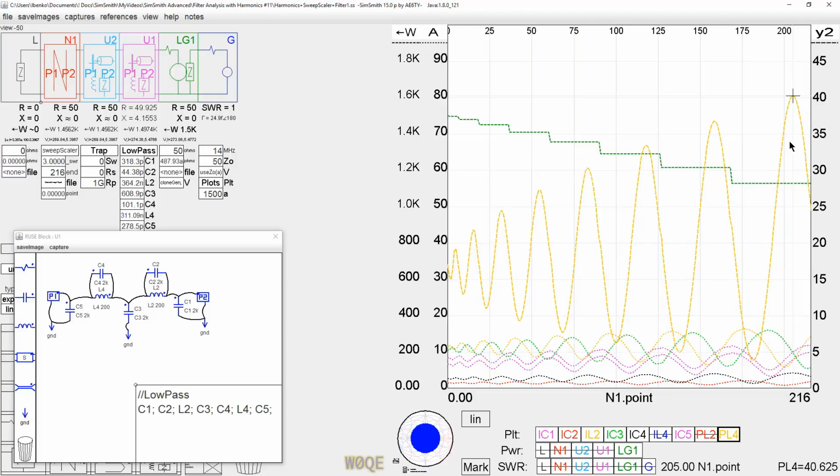We saw before the numbers were lower than those, but this is the effective SWR. The power in the inductor down here at low SWRs would be no more than maybe 22 watts. The difference between 22 watts and 40 watts, if we say that's twice as much, that's probably twice the temperature rise. So we have a way to size the component now.